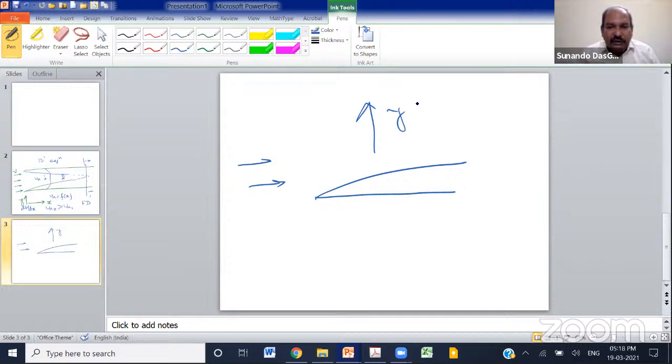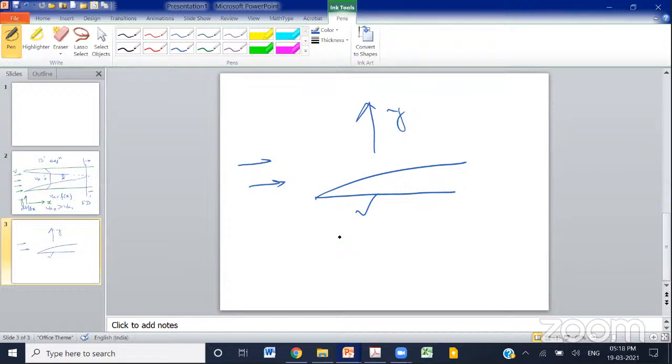The length required for viscosity to bring the fluid to rest is very large compared to all the dimensions of the surfaces that we encounter in our common engineering applications. What was the second part of the question? Why is the boundary layer separation earlier in laminar than the turbulent layer?